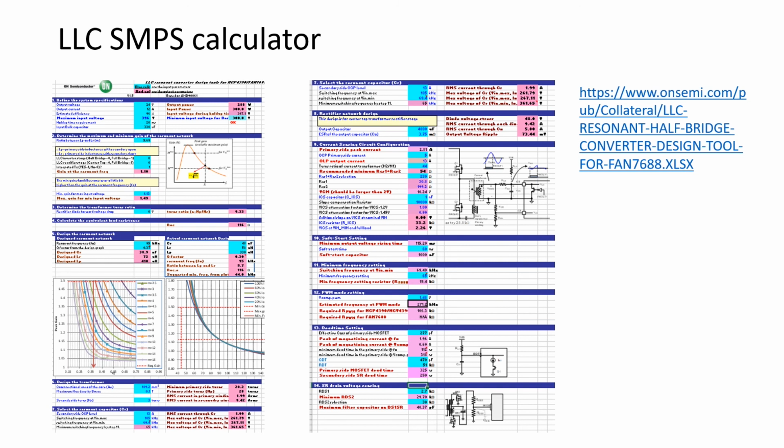10 years ago I participated in designing an LLC switching mode power supply with hands-on. Calculations are rather complex, and LLC driver chipset manufacturers support designers with online calculators. The practical design consists of the first calculation, after which you get reference values of the resonant tank. Then you physically wind the transformer based on calculated values and find out what the realistic leakage and transformer inductivities are. After that, we do several calculations until getting figures of what we can achieve in practice.